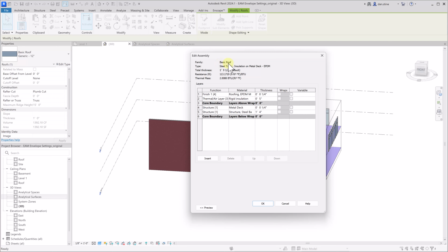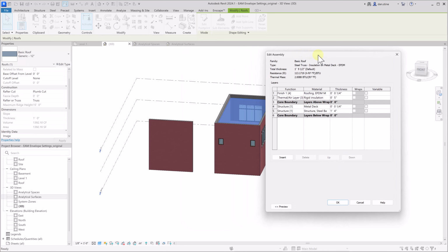So if we were using this roof but didn't want this R value to actually be included in the energy analysis model, and if we had detailed items checked in the energy analysis dialog, because we want the walls to be used, we can actually manipulate this. If we're not using it for energy modeling, we probably don't need this R value for anything.